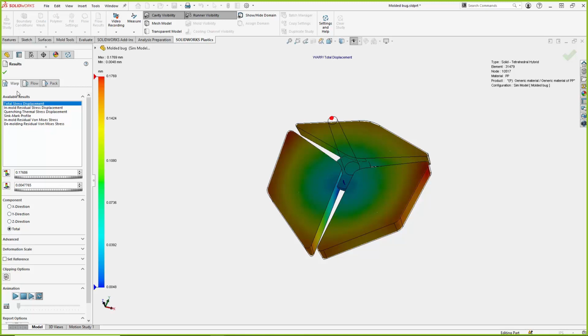In the injection molding process, you've got cooling fluid or water running through your mold. You're cycling this hot plastic in and out of the mold. The mold opens and closes. Sometimes it's open longer than it's supposed to be if it's not running automatic. Then it closes. So you've got these cycles of heat going through the mold. So you're never going to have a completely uniform mold temperature, and that's where the cooling analysis is important when you start looking at warp.